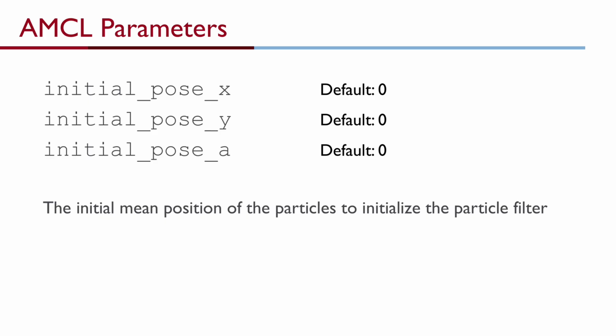In practice, you might manually set the initial pose in RViz by clicking the Set Initial Pose tool, but AMCL also lets you define it directly inside the launch file. This is especially useful when running automated experiments or repeatedly spawning the robot at a known starting location.